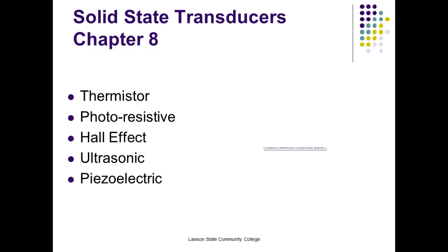Positive, okay. A negative, an NTC is a negative temperature coefficient. What would you think that guy would do? The resistance would go down with temperature. So it pretty much falls into line. These guys here are not hard to understand, but they're all over the place.